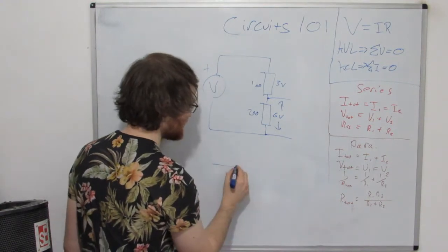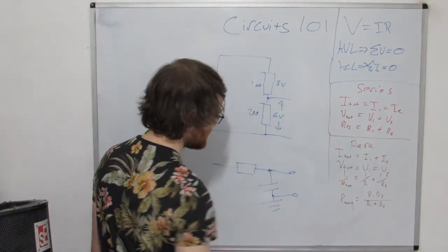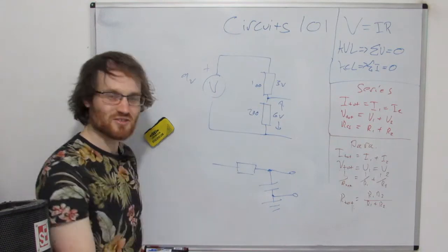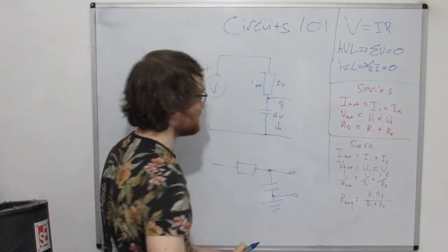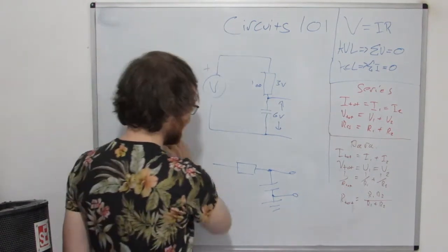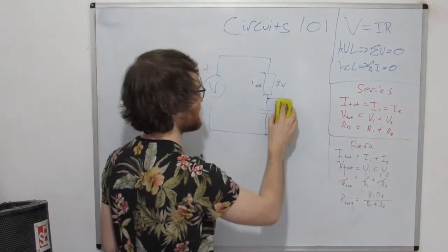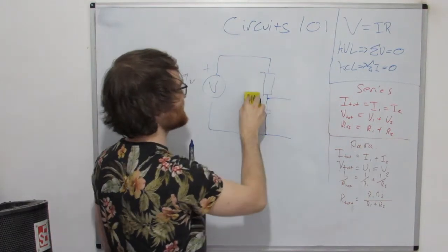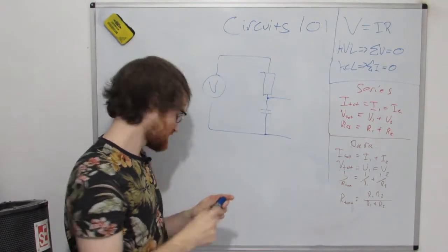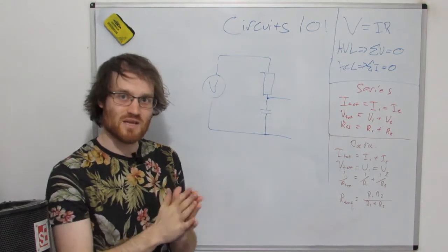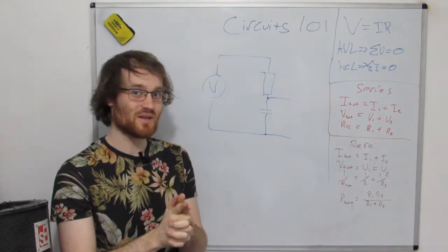Well, if I draw a filter down here, you can see now that this is just that. It's just drawn funny. If you move that there and you replace this with this capacitor, boom, you've got yourself a filter. And so, how come this just does a voltage division, but if you put a capacitor in there, it becomes a filter magically? Well, the reason has something to do with probably the most misunderstood thing in all of audio electronics that we're going to talk about now: impedance.